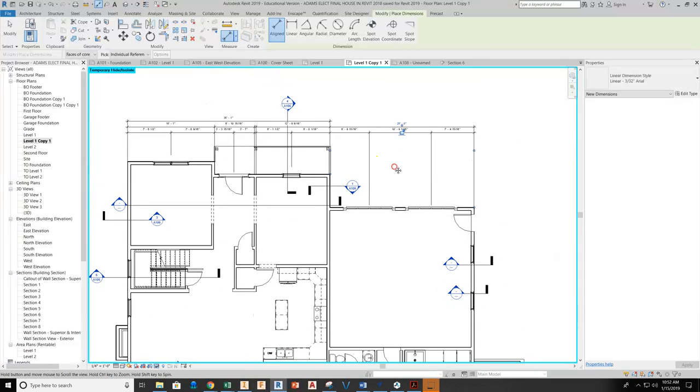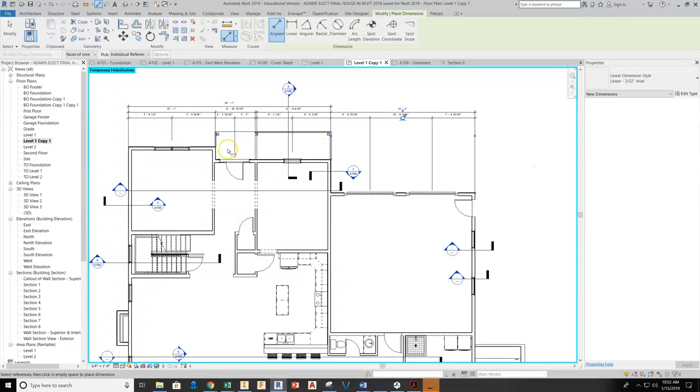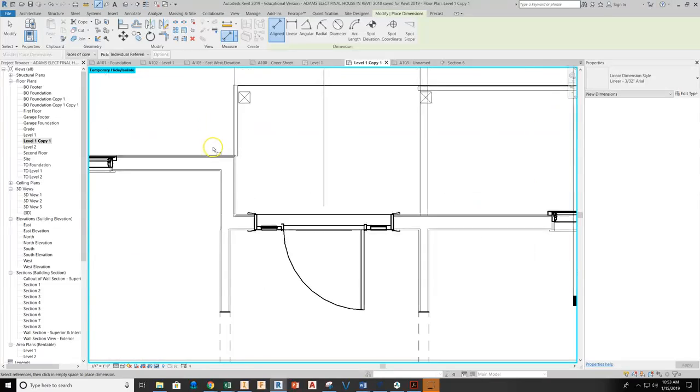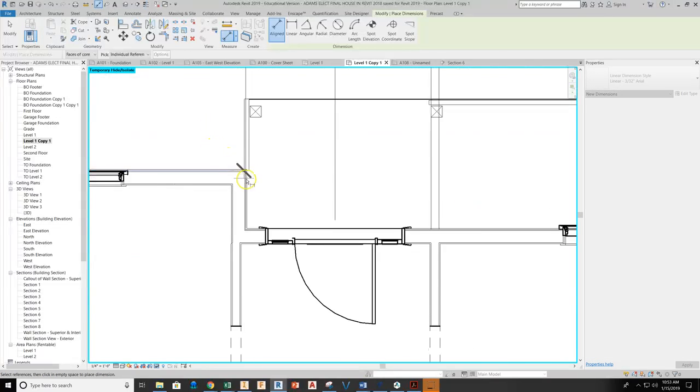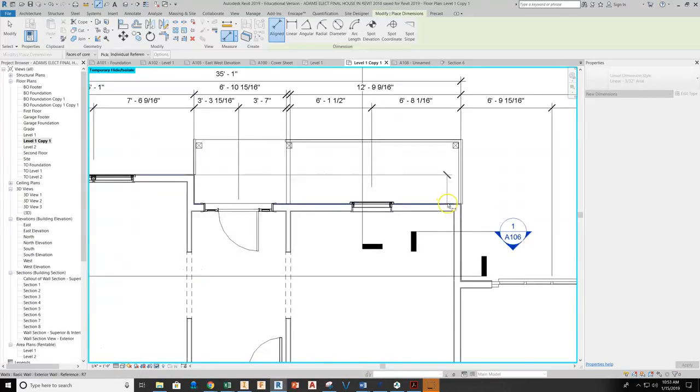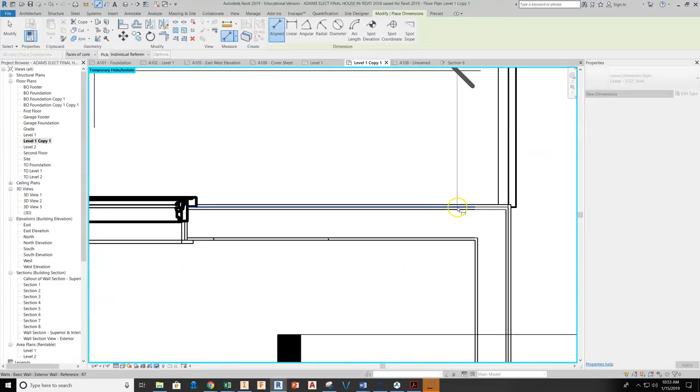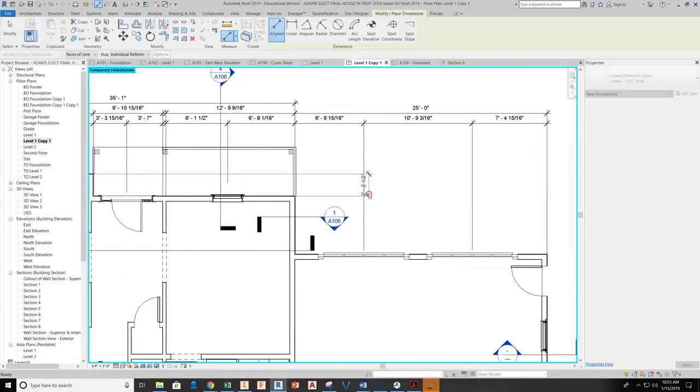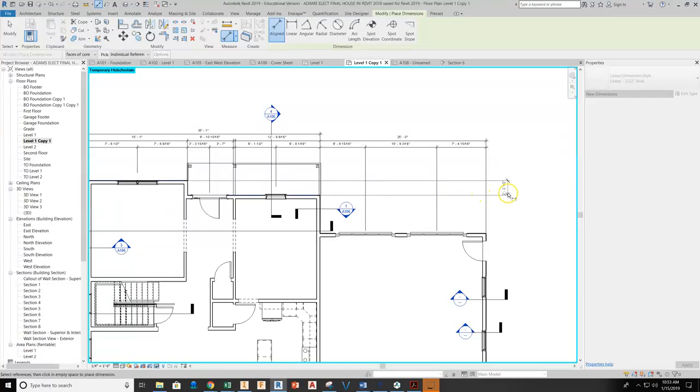Now, what I'm going to start doing next is start positioning dimensions for the front of the house. And what I'm going to do is actually pull these dimensions from the sheathing face. I'm going to pull out to this point, and I'm going to come to this edge of the sheathing face. And then that dimension is going to get pulled all the way past the edge of the garage, or past all of the extensions for this garage.